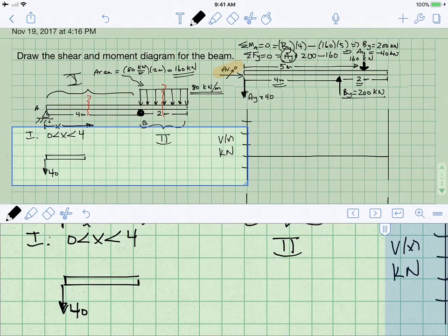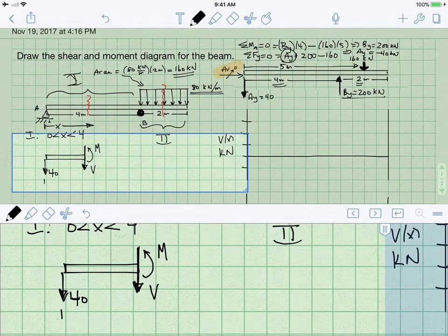I've cut the beam. Because I've cut the beam, I must indicate the internal forces, which are shear, and we always, on the left-hand side of the beam, draw shear pointing down. There are internal moments present in the beam, or possibly present in the beam, and that's it. I have no load occurring between 0 and x. So let's also just write that x is going out to here. And so now it's actually kind of simple.